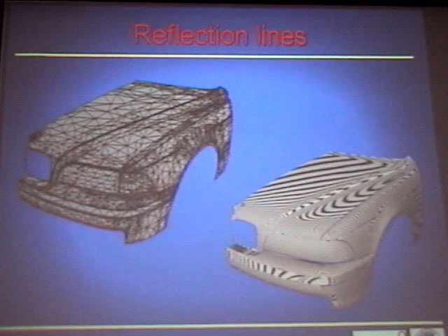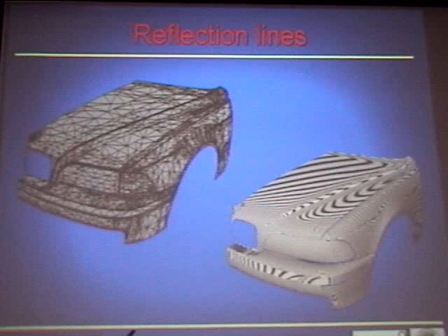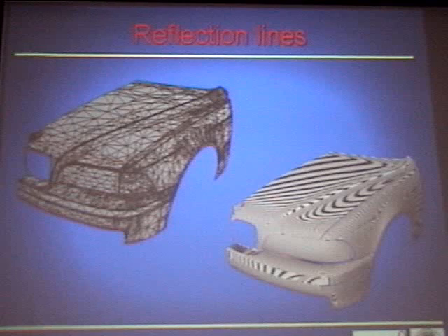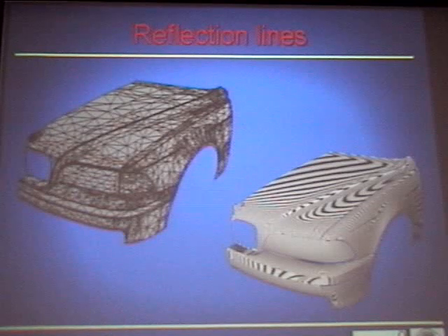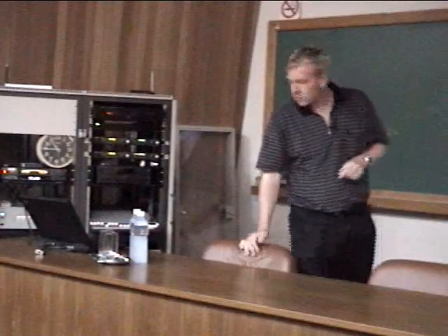And then, of course, your mesh decimation algorithm has to take care that the reduction is done in a way that the triangles are aligned to the curvature behavior. Otherwise, you cannot hope for getting the right reflection lines. But this can be incorporated in the algorithm by means of this quality measure predicate that I introduced as my third ingredient.